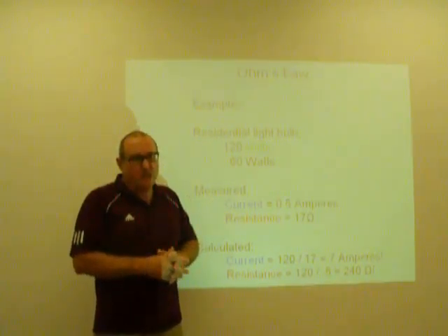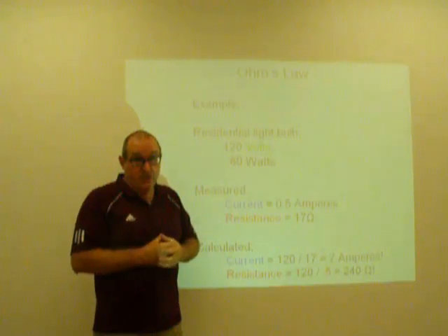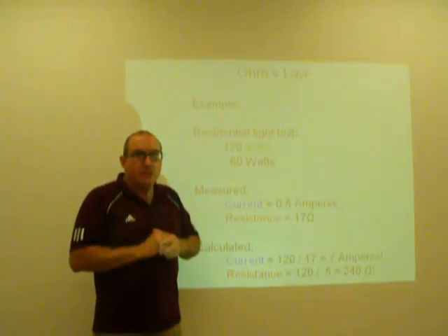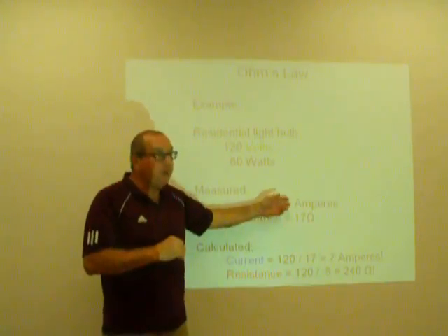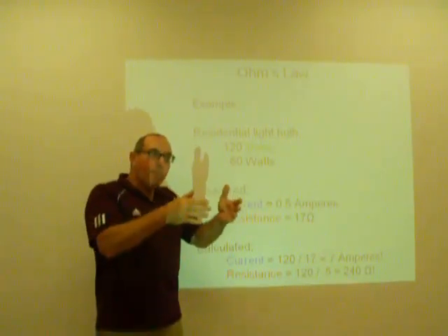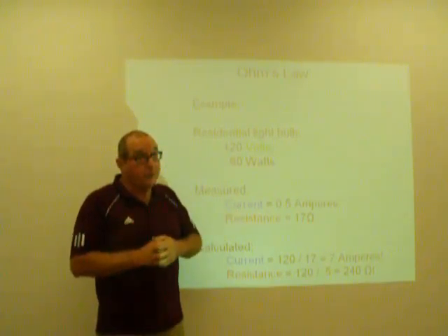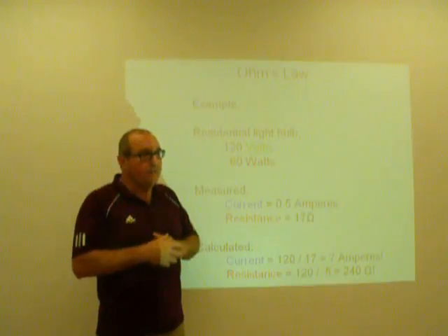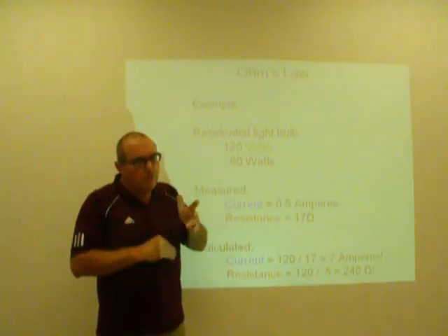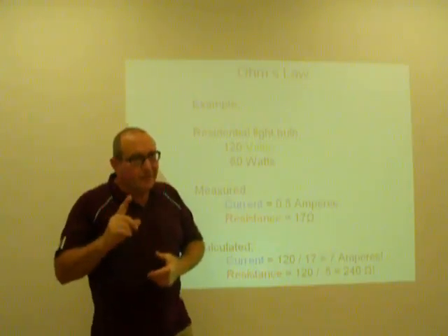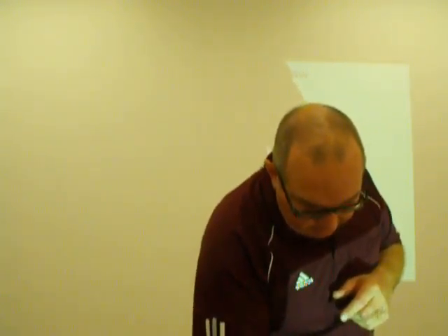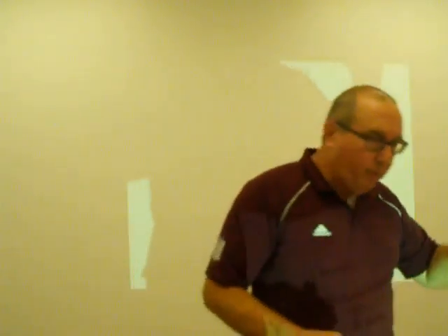So as that bulb heats up, the resistance increases until it stabilizes at the resistance that results in the measured current of 5 amperes. Now we really can't measure the resistance of that light bulb when it's operating, especially at 120 volts. What we can do is, since I've let that light bulb operate here for a minute or two while I've continued talking, I can very quickly unplug the light bulb, set up my meter again to measure the resistance, and see if I can get a much closer number, just so that it looks more realistic.